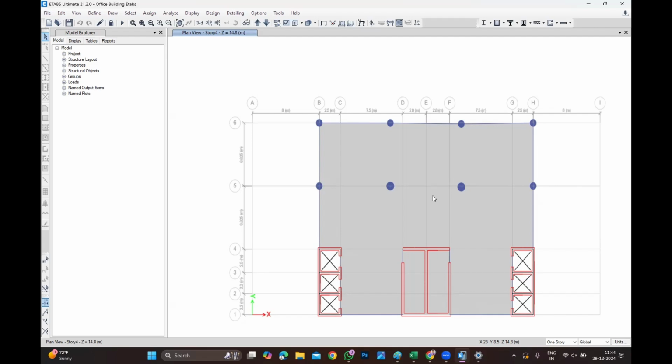Very important. Since it is a fire exit, where some of the people are going to stay, it has to be an RCC wall. The reason why RCC is used is that it holds against the fire for at least 2 hours. Other than this, nothing. You cannot give the guarantee for block at all. So the CR is going to be based on the lateral stability system. You should be in a position to say which kind of lateral stability system your building has. If you don't have a shear wall, it is completely frame, and all the columns are going to resist 100% of the forces.